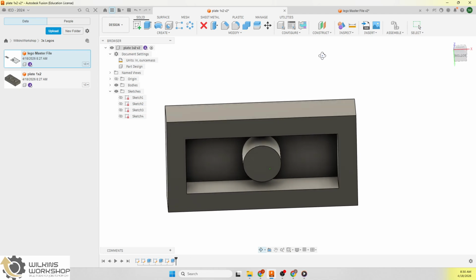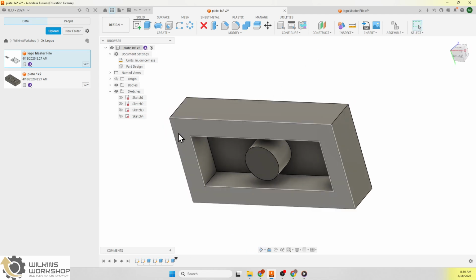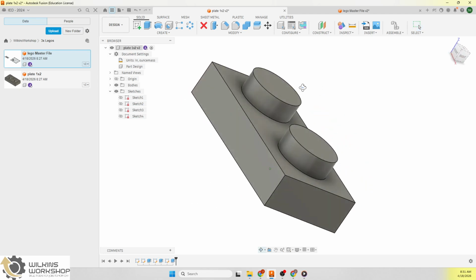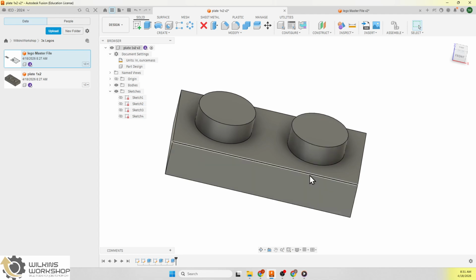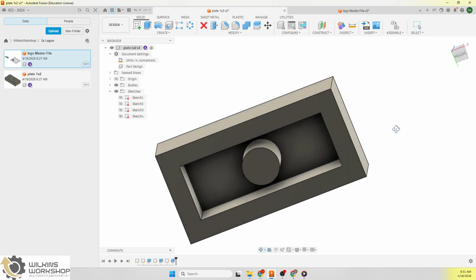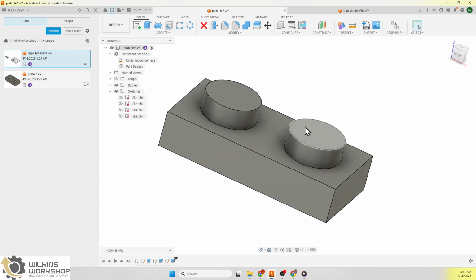That's because of the injection molding process. They're essentially using a shell to make these parts. Because we're 3D printing these parts, most of the upper section here is just air because we're using an infill of about 8% when we print. So it's not a solid part. If you're going to make this a solid brick of plastic, absolutely, you'd have that extra detail because you want to save money on materials. But for us, it's mostly hollow anyway.